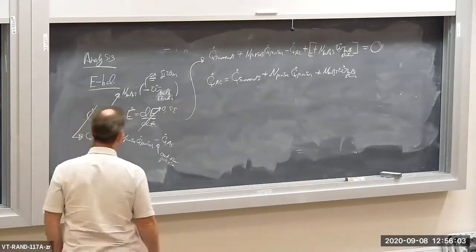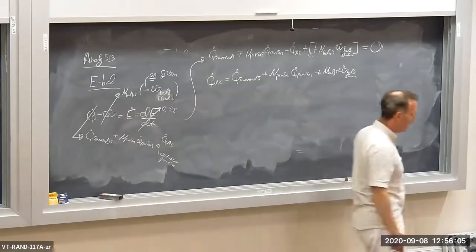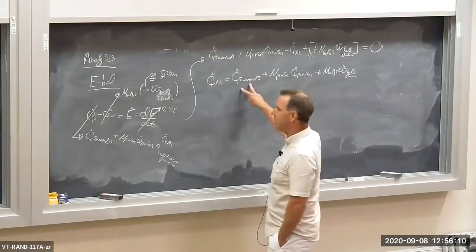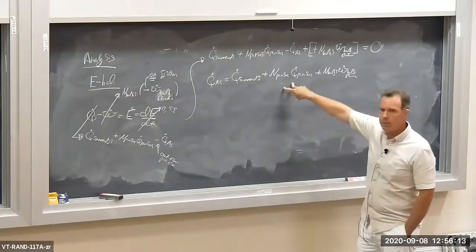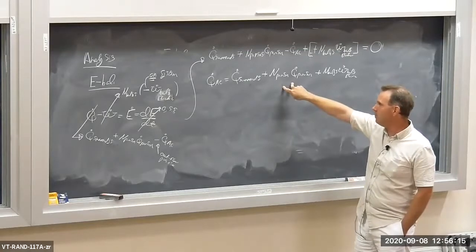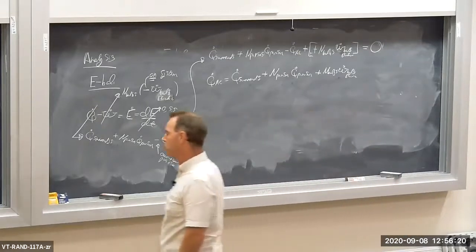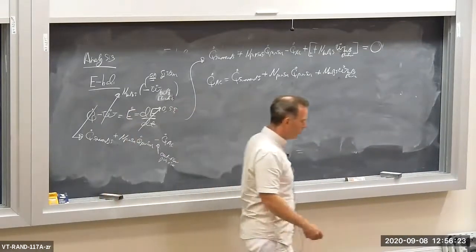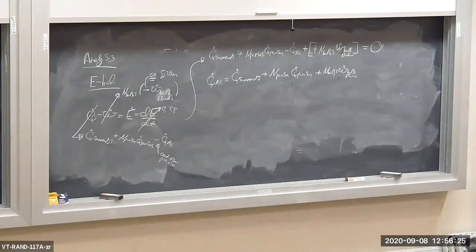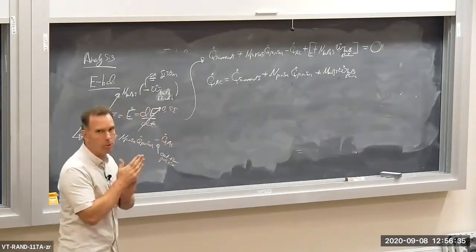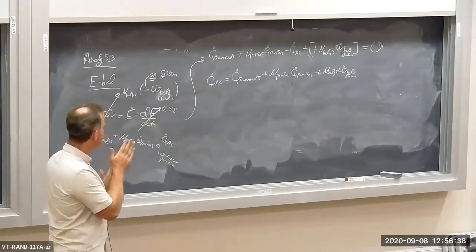So now I have an expression for the amount of heat that must be transferred out of the room due to the AC unit. It's the heat transferred in due to the environment, the heat rejected due to body heat for all the people, plus the energy dissipated or consumed by the electric bulbs. All the energy that flows into the room has got to be transferred out due to the AC unit. The AC unit's dumping all that energy that's flowing into the room back out into the environment.